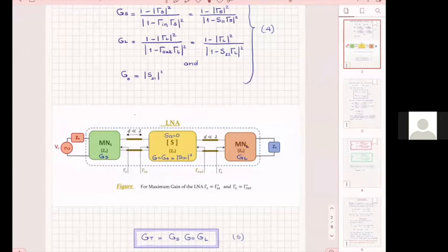Also, for high frequency circuits, the common thing for every designer is to use transmission lines. There are many advantages of doing that, because introducing lumped elements may not necessarily be possible for the frequency, the substrate you're using, or the fabrication. Usually transmission lines have shown to become the better way of doing designs.